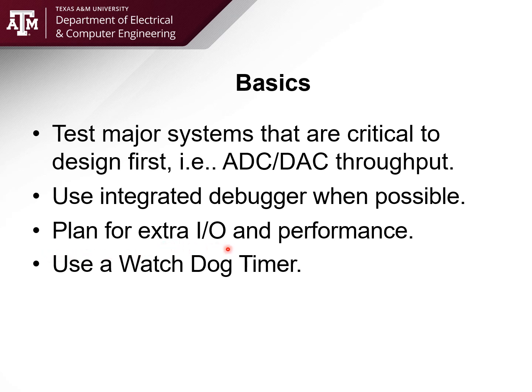You need to plan for any extra I/O and performance. This is something that people, again, lack and don't do. They go exactly off the requirements. I need 10 I/O lines, 2 A to D lines, and 1 D to A, and they get exactly that. And inevitably, if you are an engineer and you work for an R&D company, well, the research part of that, you're a research scientist, it's research. They don't know exactly what they're doing. So they're working on the bench. Adding another temperature sensor and a process diagram is no big deal to them. They just add another thing to their LabVIEW setup. It can support another I/O.